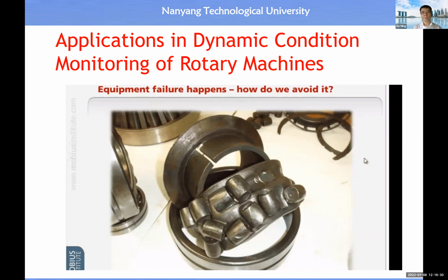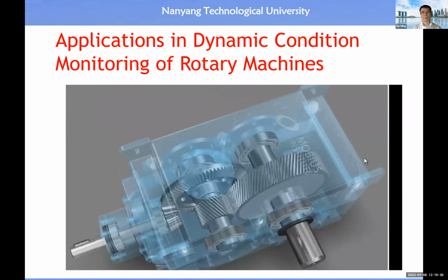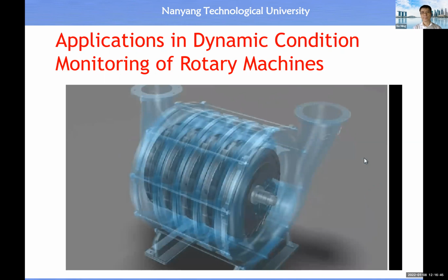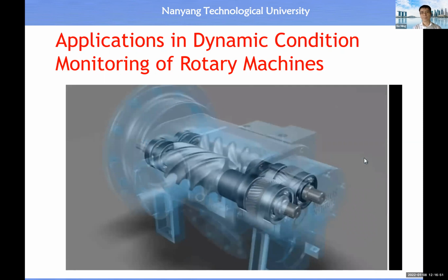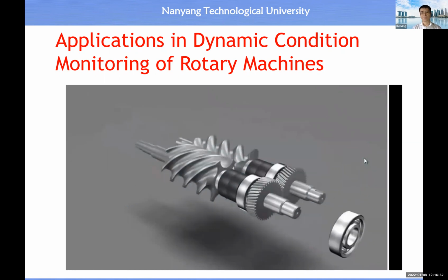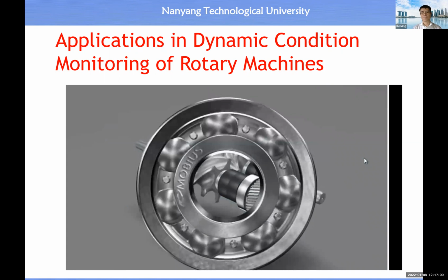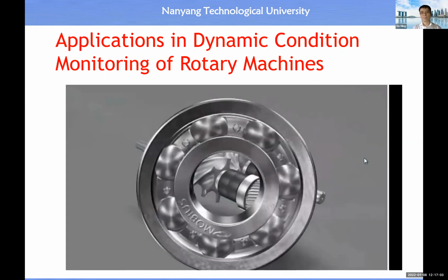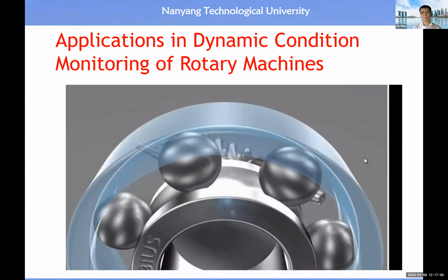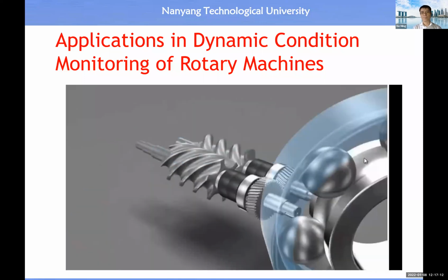And vibration analysis is a terrific tool for doing exactly that, because vibration analysis, in a sense, enables us to look inside the machine and see exactly what's going on, whether it's gearbox with bearings, blowers and fans and so on. We want to be able to look at those bearings, look at the gears, look at the impellers and so on, and find out what's going on. If we could look at that bearing and tell that it's lubricated properly, installed properly, there's no damage to the raceways, there's no damage to the rolling elements, then we have the confidence that we can go on producing our product and it's all good. But if we see something, then we can act.